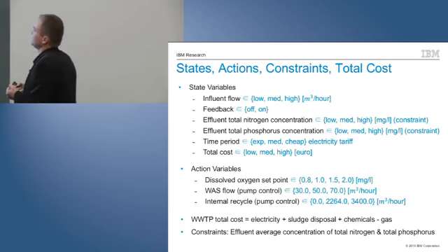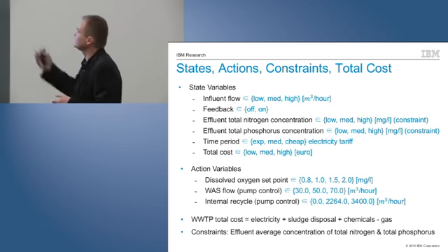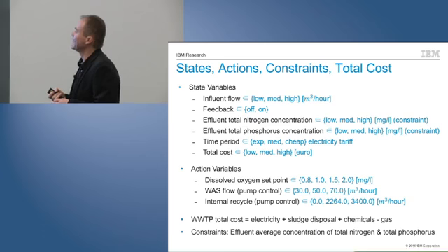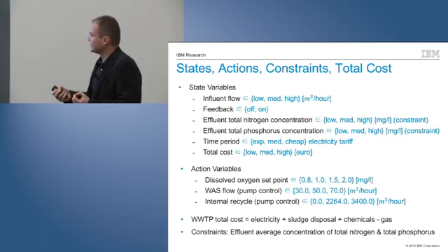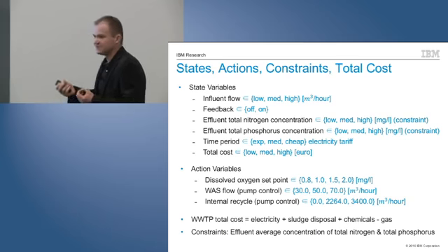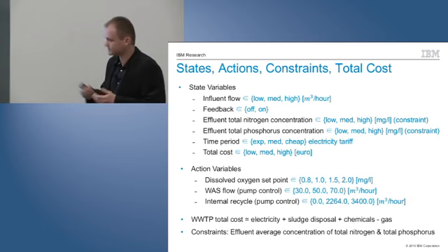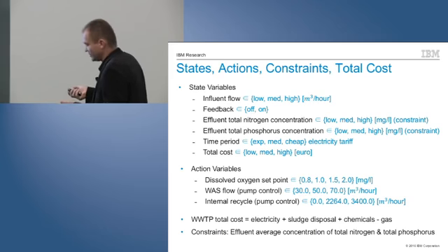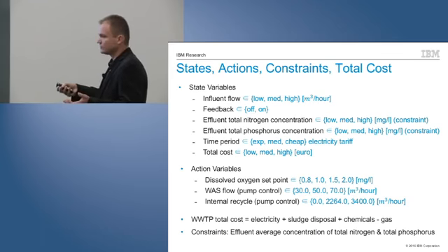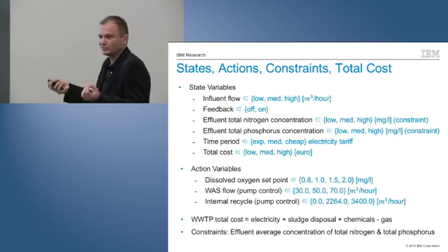At this moment, we felt quite confident to use CMDP for the solution, and we started looking for the necessary variables that must be in the model in order for the optimization model to be meaningful. If we don't have enough sensors to sample a meaningful state, we can't solve the problem by this method. The first variable that must be inside is influent flow. This is clear. If influent is 0, the optimal policy is just to shut down the plant at zero cost.